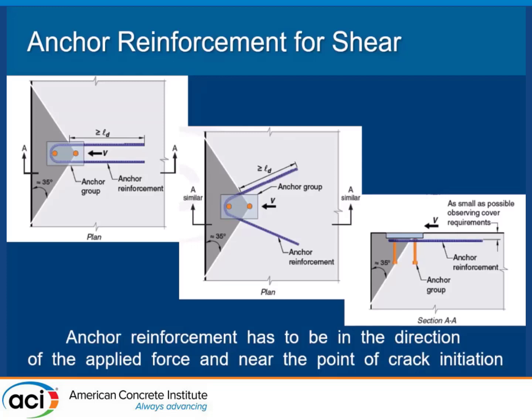Now, the great thing about shear reinforcement is if you're casting in place, so it's fresh, it's new construction, you can use a hairpin. For those of you who don't know what a hairpin is, you're looking at it, and we call these things hairpins. We use them to spread out localized stresses in concrete all the time.